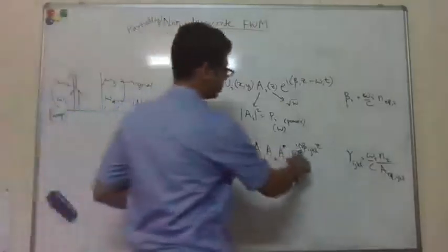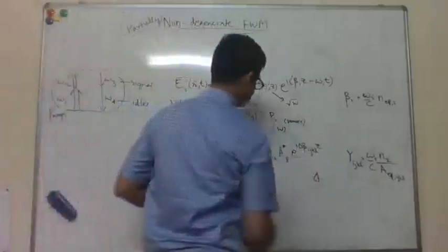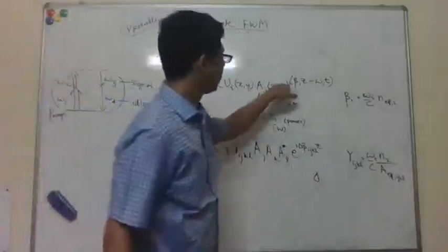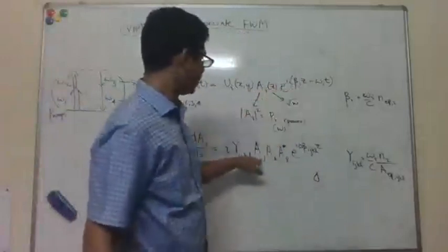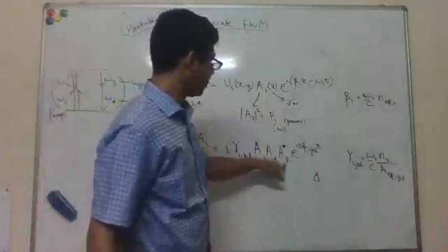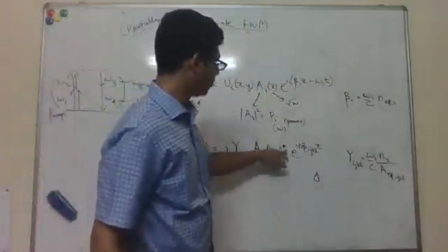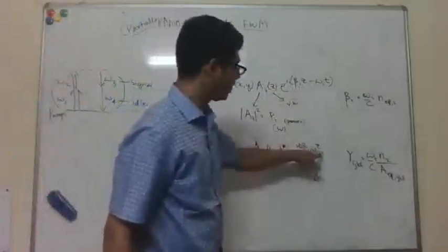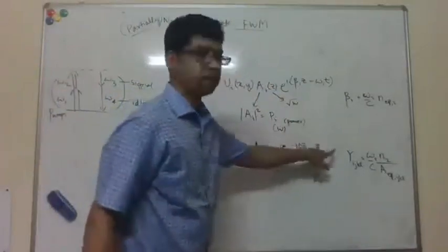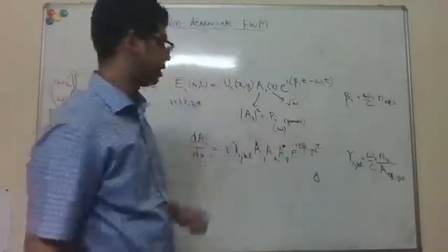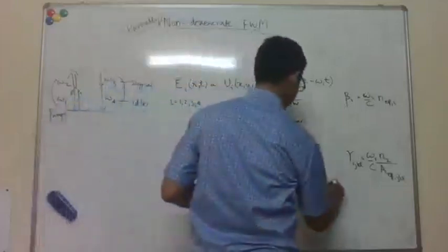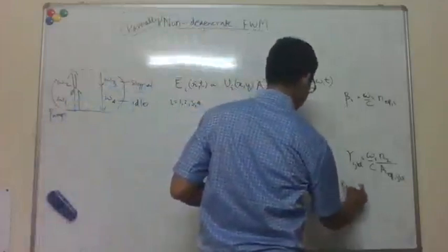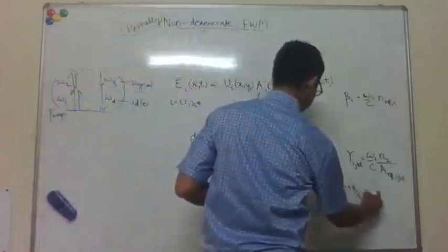And this phase mismatch factor here: we'll have the product of three fields here. Each of them will have A times e to the i beta z. So you'll have beta j plus beta k minus beta l, if l is conjugate. And then from the coupled amplitude equations, you already have an e to the minus i beta i z for i. So this delta beta is beta j plus beta k minus beta l minus beta i.